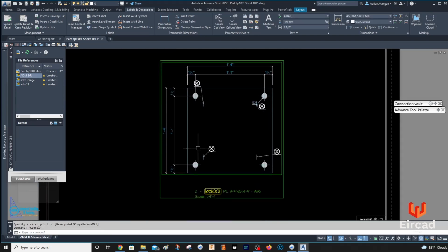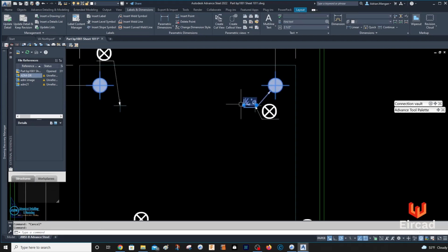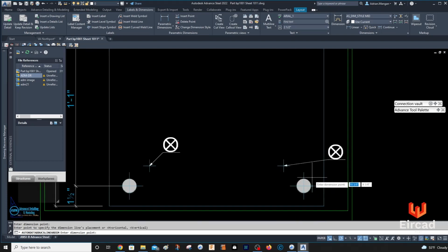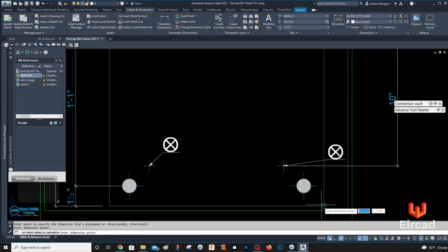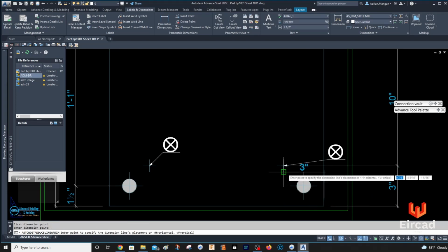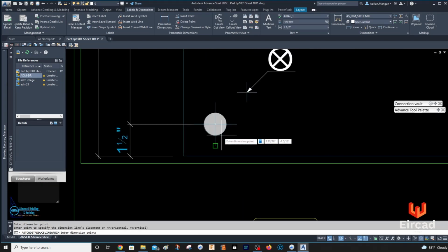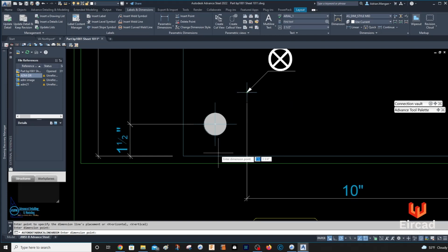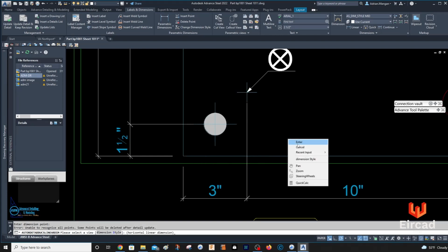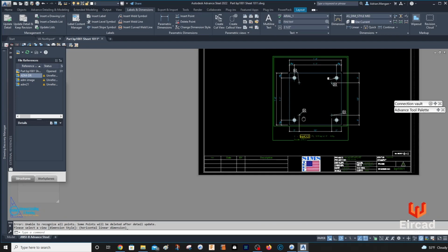So you can also have it come in with those dimensions, but if you just update it like I did, just click on parametric dimensions and just add your own dimensions quickly. If it's just the one case, it's not a big deal, right? Just add it in. I'm going to be opening the drawings anyway to check everything because I don't do huge projects, so it depends how much you have to rely on.